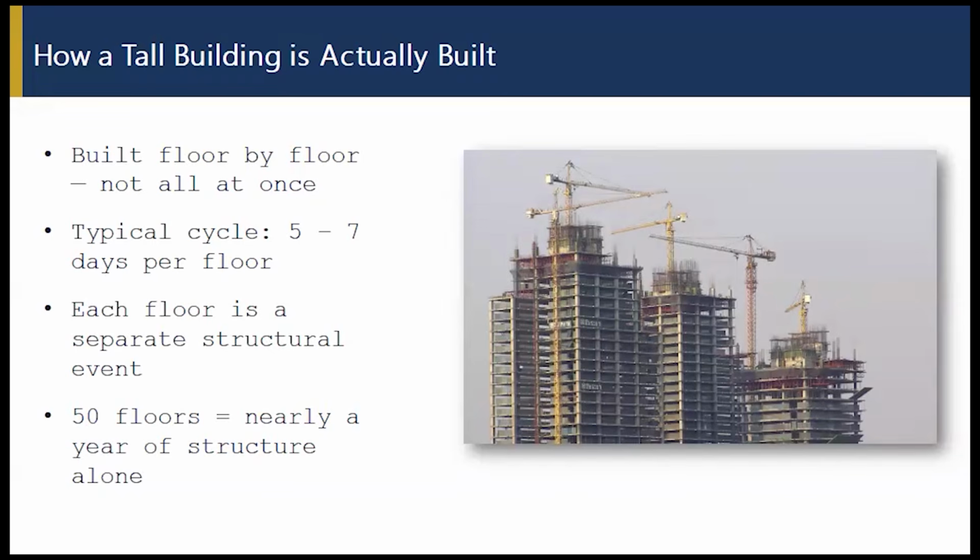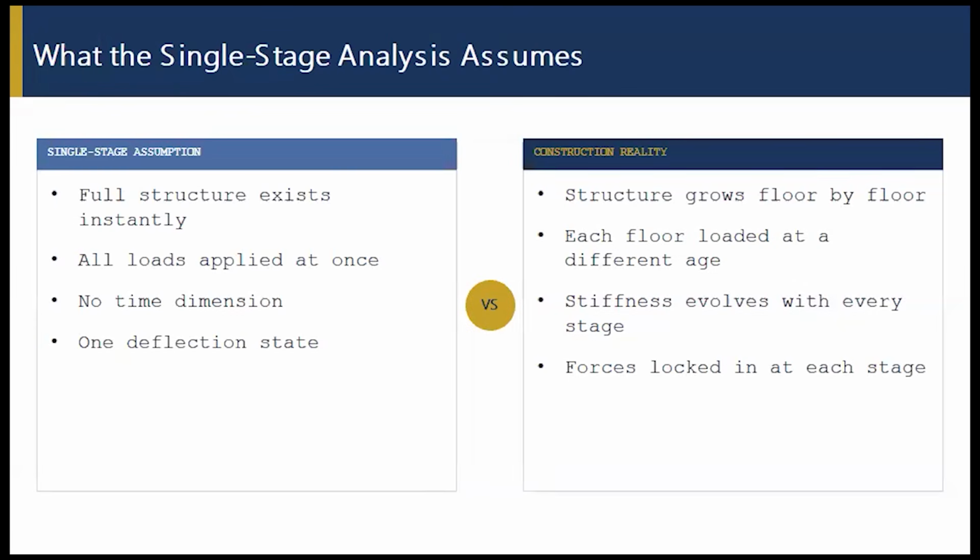And then if you just make the model for the building and run it, that means you're only analyzing the completed building, which is not the same as what happened during the construction. And those two are very different, we will see, especially for tall buildings. For small buildings, it doesn't matter much, but for tall buildings, it matters a lot. But even for a small building, I will show you.